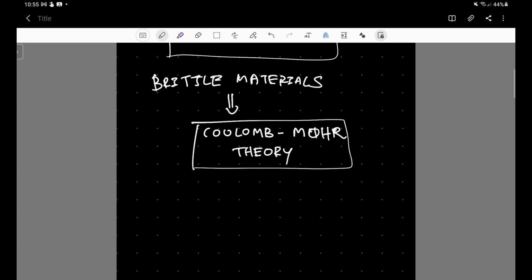connection with bending problems. If you use constant strain triangular elements for modeling bending problems, the elements will generate a model which is stiffer than the actual scenario, because the term constant strain is not really applicable for a bending problem. In bending problems, the strain will change linearly within the element.